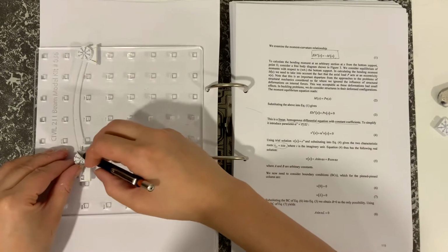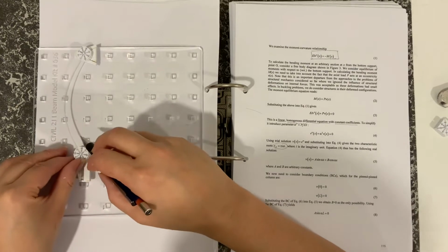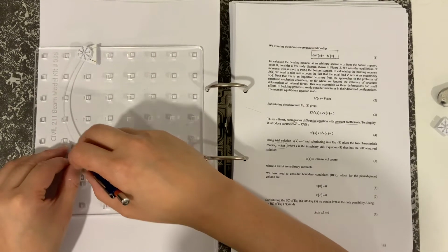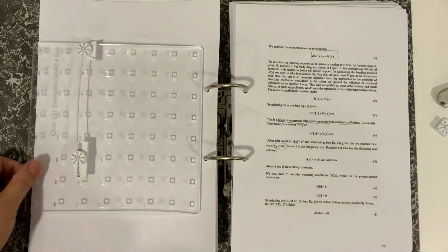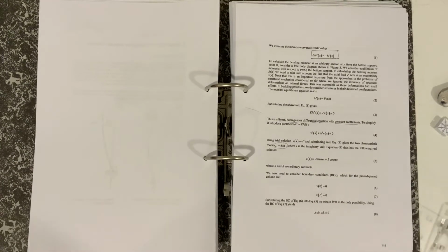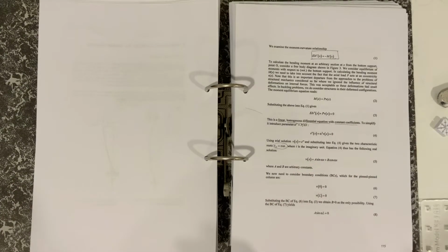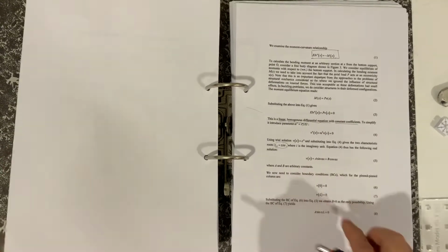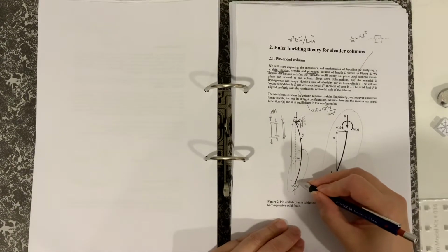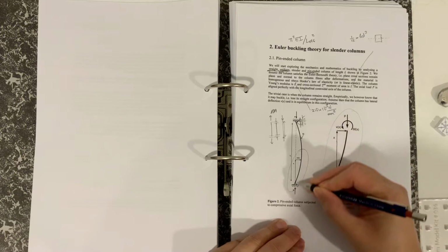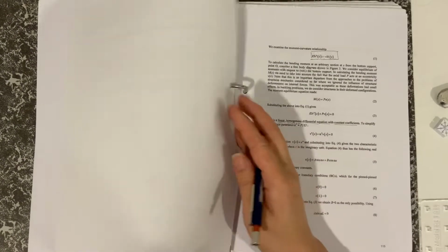And the important thing is that you can observe, even just by looking at it, I would hope that the buckled shape is a half sine wave. So that basically means you sort of knew the answer before we started, that the v of x, which is the shape here, is going to be a half sine wave, which it is for the buckled shape.